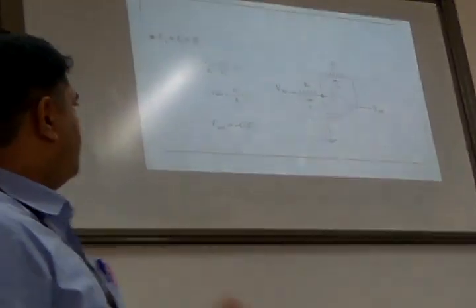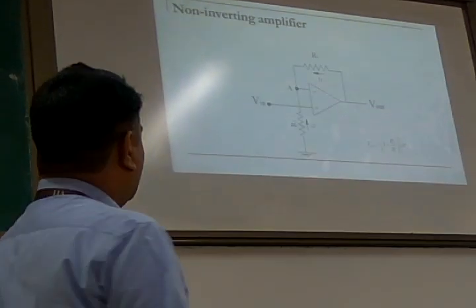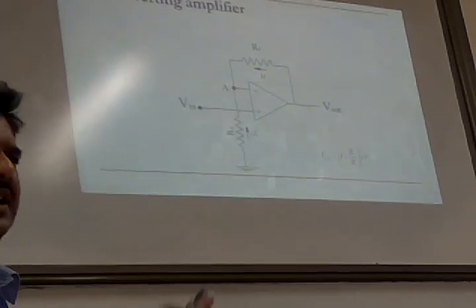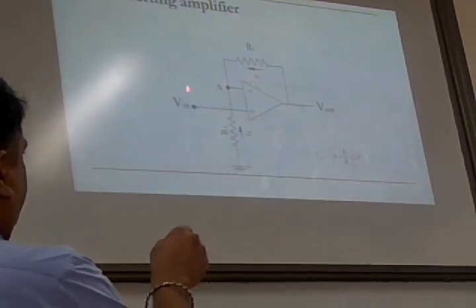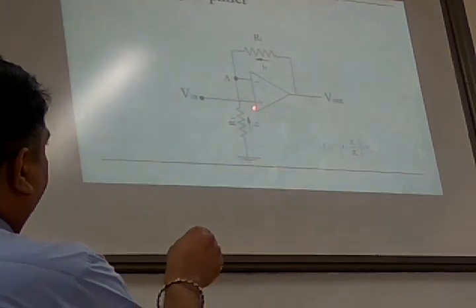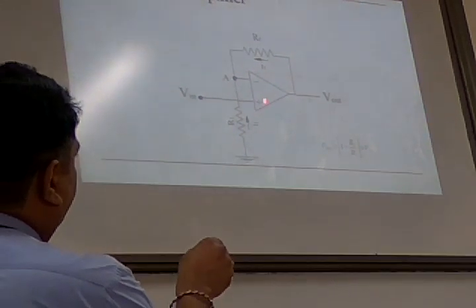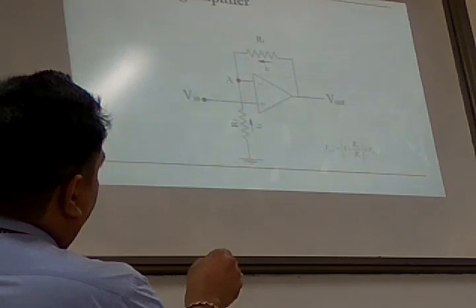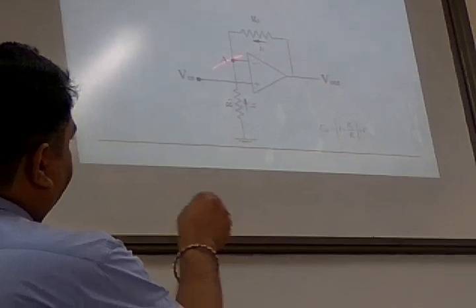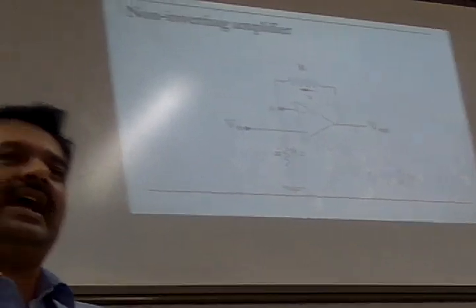Okay? No. So if you know this, the similar work, you take any LIC book, this is the non-inverting amplifier. A similar expression we can draw. Same Ohm's law, same thing you write. Simplify, you get this equation. You connect the voltage to be amplified to the non-inverting input, and the inverting input you connect to ground, and this is RF, this is I, and so on. This circuit configuration is the non-inverting amplifier.